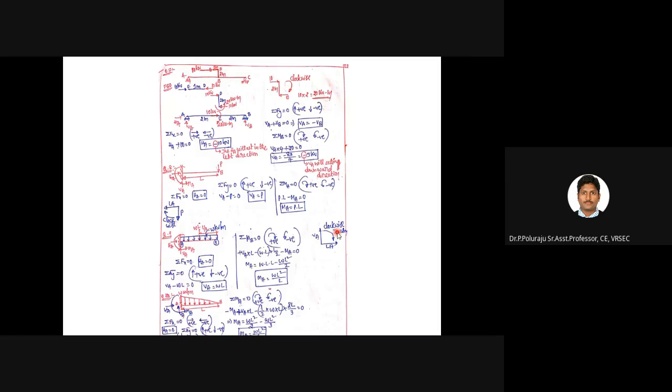Question number 7. Yeah, this kind of problem is also possible because the load is not acting at the tip of the bracket vertically. It is acting at the tip only, but horizontally. Then how to convert the load into your moment? So here, there is already 10 kilonewtons. There will be one horizontal load here, and again this 10 kilonewtons into the transverse distance, like lateral distance, 2 meters actually. So 10 into 2 will become again one anti-clockwise couple over here.